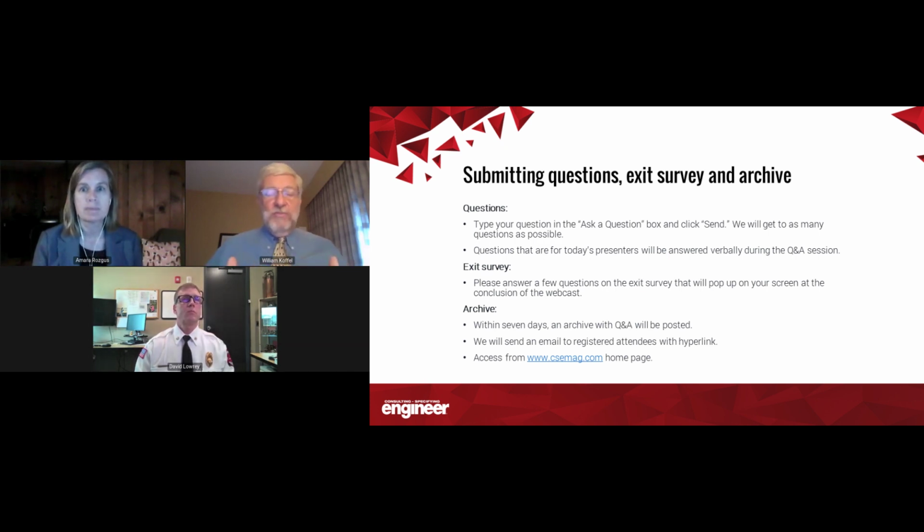So that's a great example of why I'm encouraging you to think about the owner's goals and objectives. So the code perspective, depending upon the occupancy, if the code assumes that the occupants are awake and alert, the code generally assumes that the occupant is likely to detect the fire, maybe even before a detection device would detect that fire. And the sprinkler, in particular, it's a fast response sprinkler, is likely to respond in time that we will have adequate egress time for that building. So that's kind of the underlying concept.